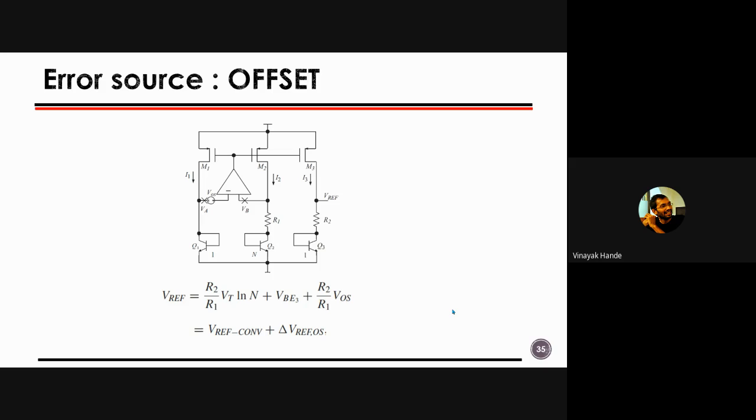Yeah, and amplify it further, and after that again dechop it. While dechopping, offset will move to the higher frequency, and the input signal will come to the lower frequency, and then put your low pass filter and done, right? So that is one way we can do the chopping.